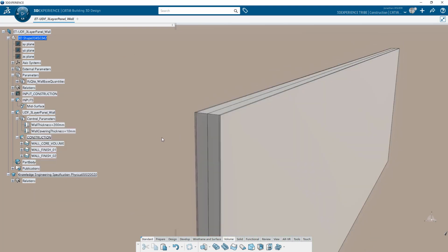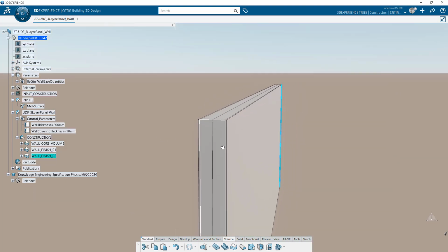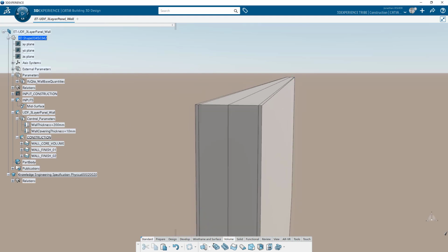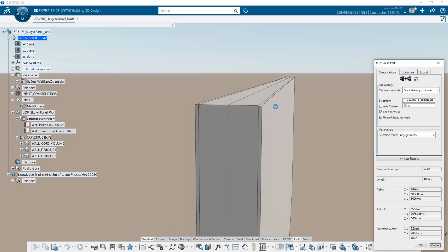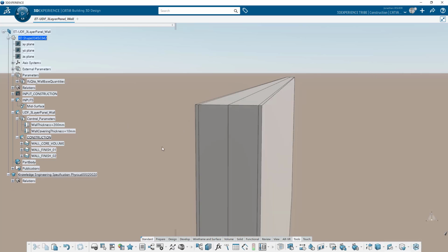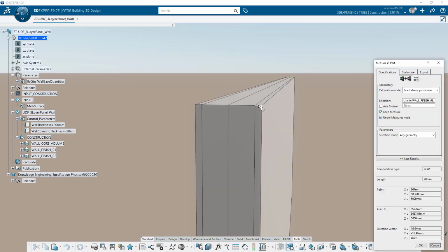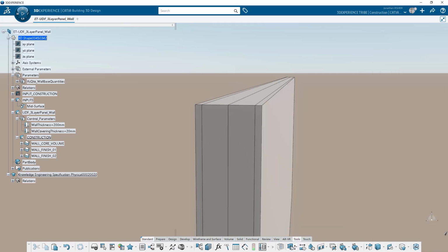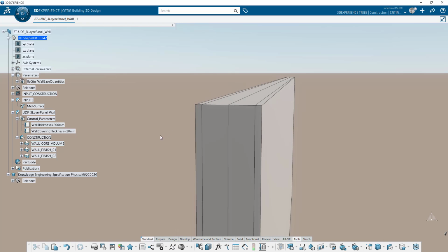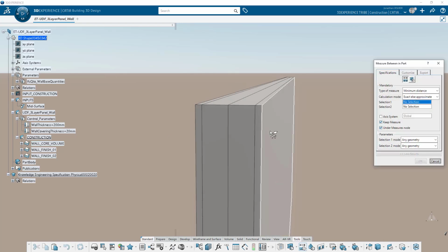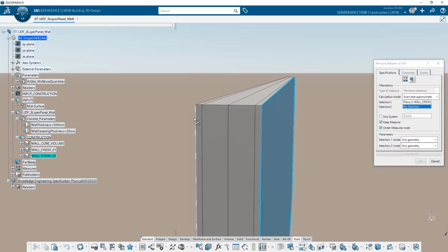And they're all inside of our UDF geometrical set so that we can easily create the UDF from this geometrical set. And we'll verify that the geometry is correct, which means that our formulas are correct. And when we change the parameters, we see the thickness of the wall coverings update. And we'll do a double check here to make sure that the thickness of the core is updating as well, and it's the correct dimension. And a last check. This is good. This is a 200 millimeter wall.